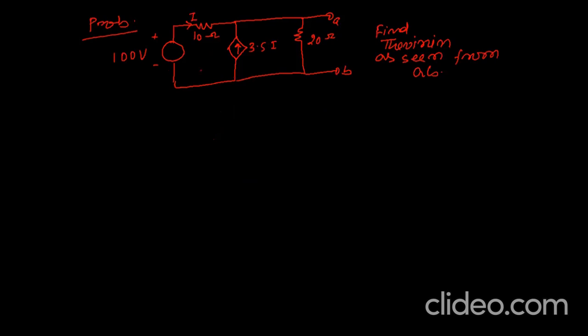So how can we find the value of RTH? It is a problem only with RTH because we cannot short these dependent sources, because shorting is not allowed for dependent sources, since its current depends on some other values, and opening of the current source is also not possible. So calculation of RTH is not possible by the earlier method, whatever we have studied.